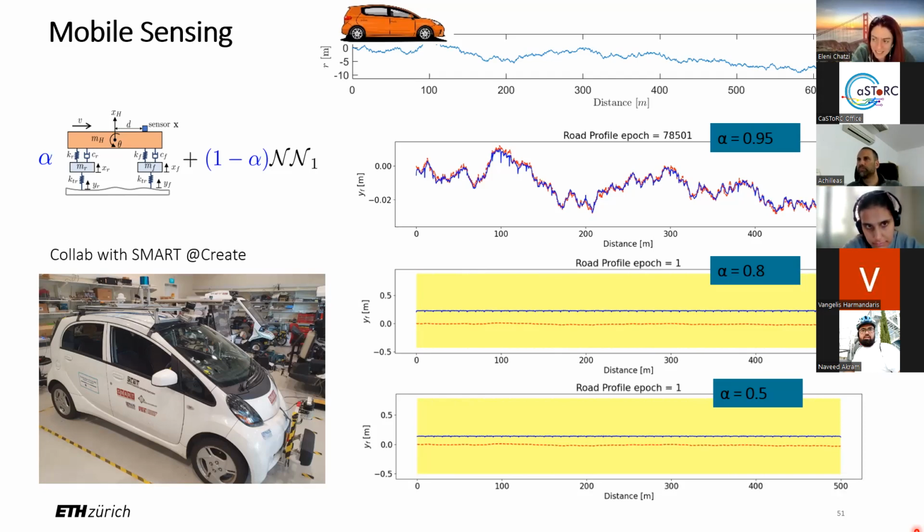In that case, the environment of the sensors themselves is basically part of that condition indicator on the robustness. So if something odd is observed with respect to the sensors themselves, it would add to that statistic and would try to issue an alarm that prohibits us from using the prediction as it should. There are different schemes, but what I can say is that it's always good to design a sensor distribution that is to some degree redundant.